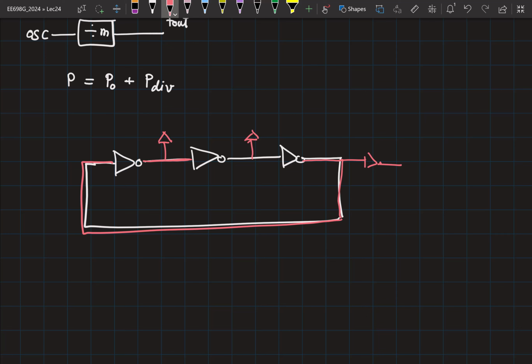Symmetrical. So how do I make it symmetrical? Okay. So generally we prefer 90-degree routings in a layout. Right, you have all done standard cell layout, right? So you don't do 45 degree, 60 degree. So it's all horizontal or vertical routings. So given that information, how would you?